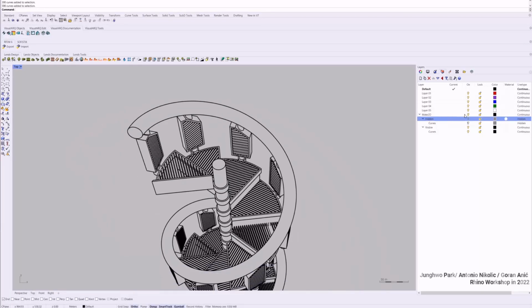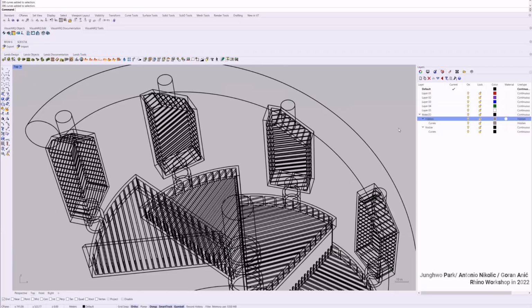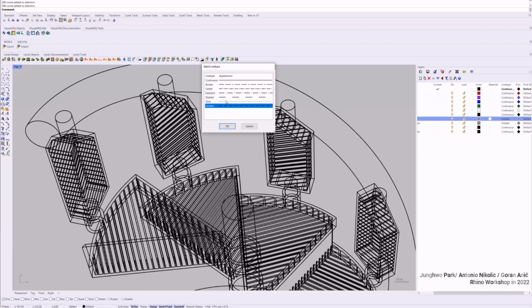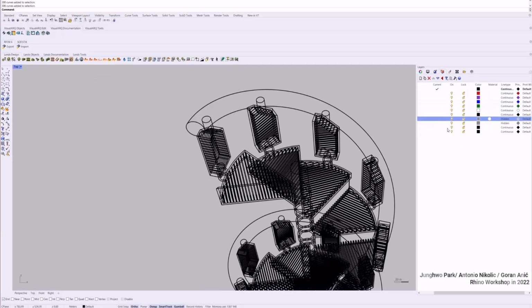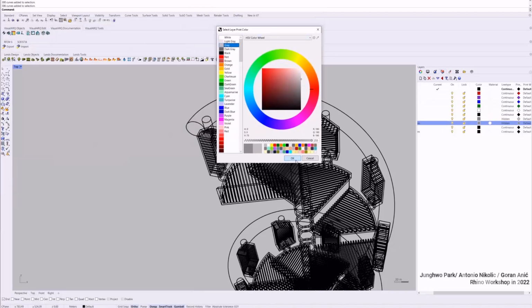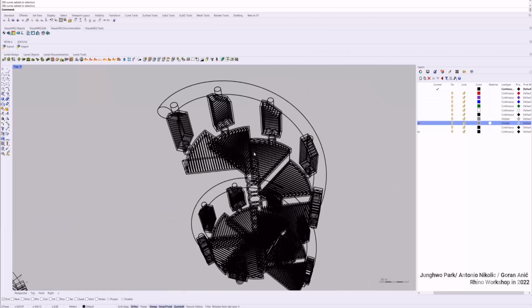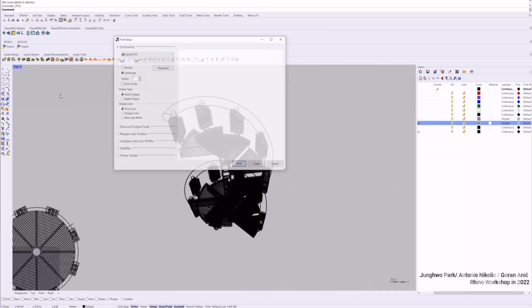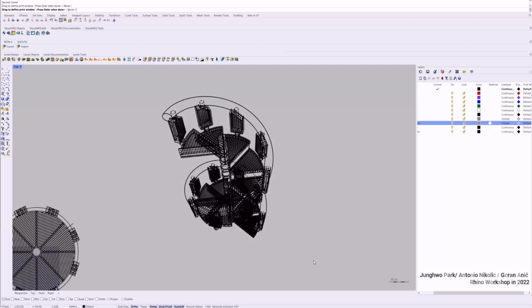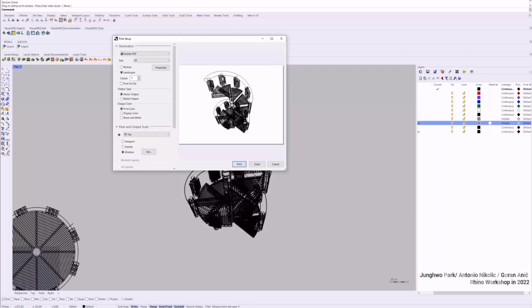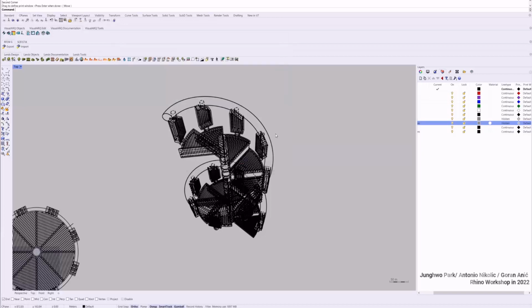And if you enable hidden line, these are the hidden lines. And you can make it really fine, and change the color, I don't know, gray. Those hidden lines and curves, I'll make it a bit lighter gray. Now if I PDF, I'm not gonna PDF but just gonna show you the drawing area. Set window. You see already there is a change. I just cannot show you, but you know it generates drawing very nicely.